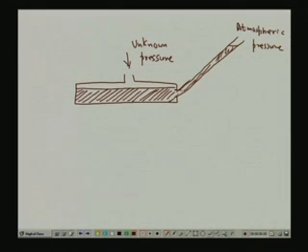You see, in the well type manometer this column is straight. Now, here the liquid, since the height is the same, has to travel a longer distance. So ultimately I am getting the advantage of the well type manometer, but the sensitivity in this case will be higher. So, I can measure a smaller pressure difference, and resolution will also be better, right. This is the advantage of this type of manometer. This is called the inclined tube manometer. You can also call it a draft gauge.